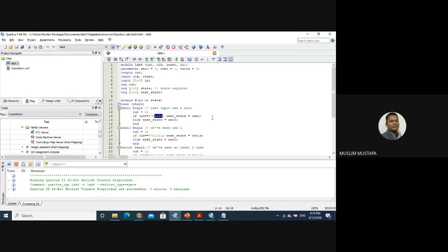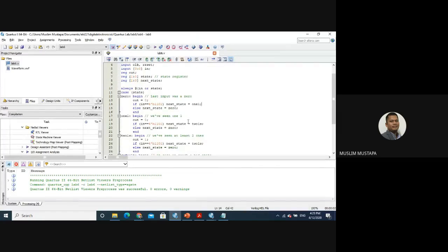Don't worry about that. Now I'm showing you examples. I think this is the simplest one for you to understand. I'm using Moore, and I'm not showing you a Mealy example, just one example. I'm using a Moore FSM, finite state machine. You see there are actually only 2 states, 0 and 1, but there's an intermediary state for Moore, because there's a difference between Moore and Mealy. Mealy has a direct immediate effect, but in Moore there's a delay of 1 cycle before you see the effect.